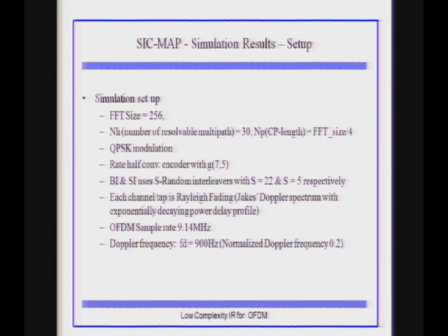So is the delay linear in S then? The larger S, the larger the delay? Yeah, the larger the S, the larger the block length would be. I don't know whether it is linear, but the larger the block length, you have to wait until the whole thing comes out, right? So that is one of the issues with turbo equalization. Complexity is one aspect of it, and the delay is the other aspect.